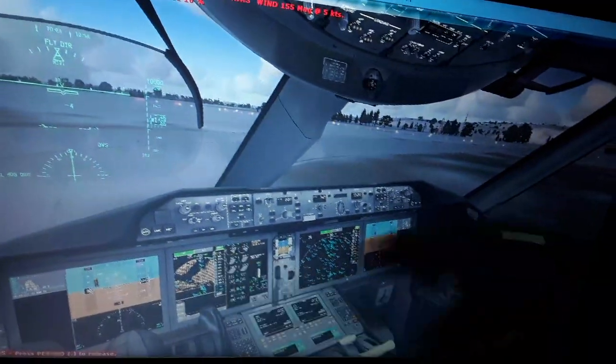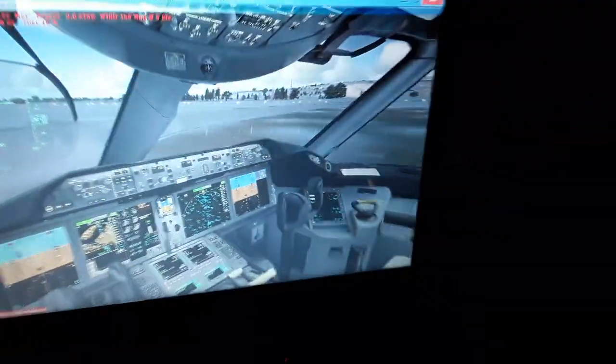Also on the ground, you can see the other aircraft on the taxiways and the runways. We can see the aircraft from the TCAS system with a diamond shape in the navigation display, and also with an altitude indication of the altitude difference from our aircraft, with a plus or minus sign. So you will see later over here in the navigation display.